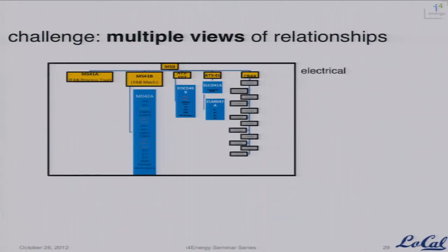So for instance, in this example, one key view is the electrical view because we're measuring electricity data here. So what's the flow of power through the building? It comes in through a 12.5 kilovolt transformer in the basement, gets distributed into 480 volt panels throughout the building, where it gets stepped down to the outlets. What's the relationship between all the meters in the building? How do you figure out where you are in that tree?